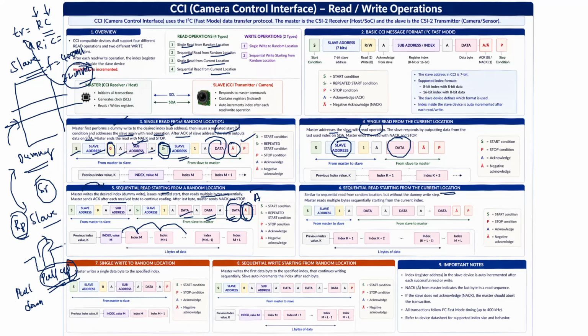Then the next master is ready to pull that high location to low. Whatever high value is there, the master pulls it from high to low. That operation it does, but low to high is not done by the master. It is done by the pull-up resistors. Once your data is transmitted fully, the pull-up resistors come into the picture. Then they do that low to high of your SDA line.